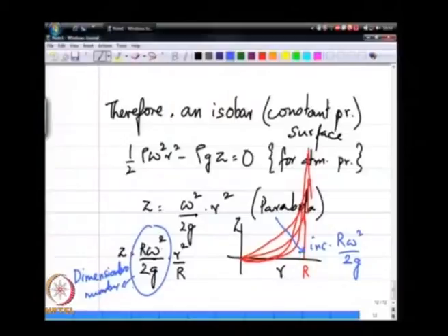It does not matter what the component of g is, you are going to get essentially what looks like the same spray. For that to happen, this r omega squared over 2g is a very large number. So what looks like a parabola in our regular container spinning is now going to look like a thin film that is sticking to the walls of the container, the walls of this exit orifice.